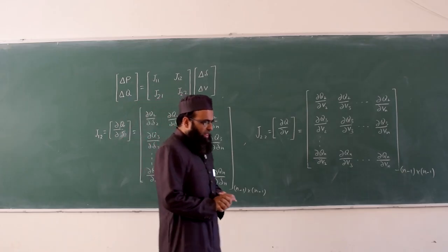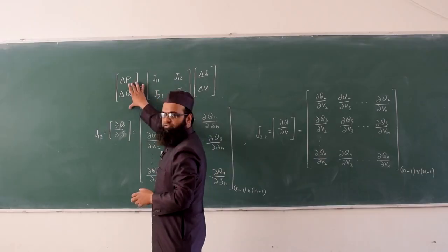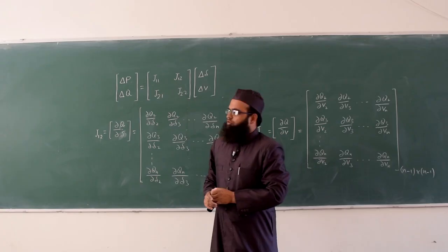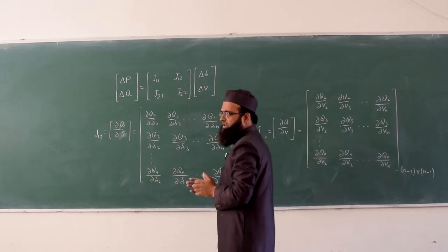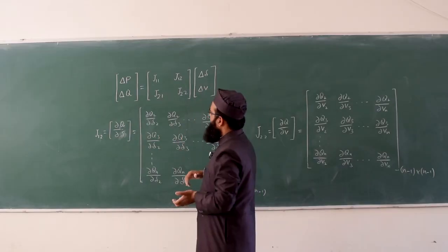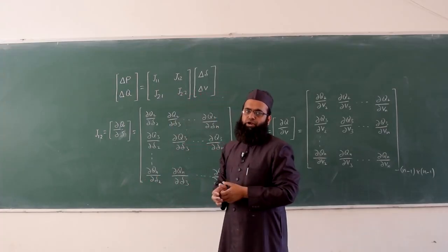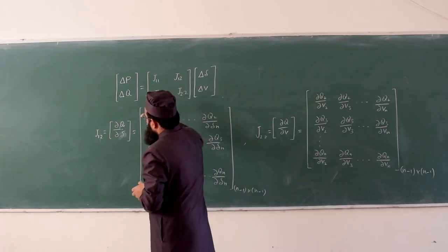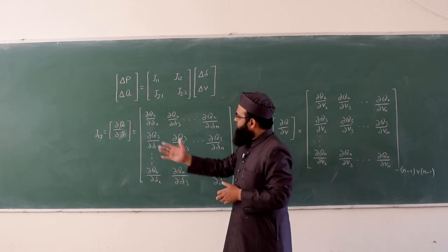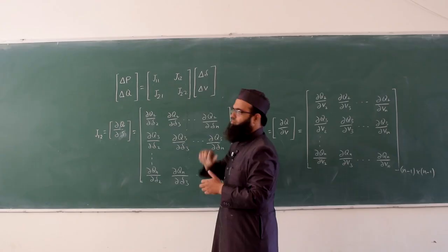So, corresponding to the specified quantities, the left hand side quantities, we are having del P and del Q. We can calculate it assuming certain initial values of delta and V, and we know del P is the difference of specified quantities and calculated quantities. So, we know this, and at initial values we can get the values of the elements of Jacobian matrix J11, J12, J21, J22.